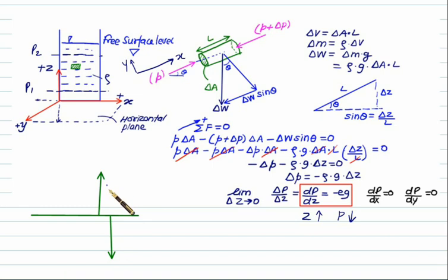If the pressure here is the reference pressure P0, we can calculate this pressure using this concept. As z is increasing, this value becomes negative, meaning the pressure will drop. So we write P0 with reference to this pressure, and since z is positive, we replace this value with minus rho multiplied by g multiplied by z.